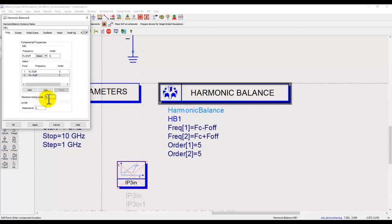So here for my analysis, I have set the maximum mixing order which I want to see in my results to 7, although I could have gone till 10. But for any practical purpose, there's no fun in going for more than seventh order products, to be very frank, because these products themselves are far from our carrier frequencies or the main tones, and anything beyond that can be easily filtered out, and they are pretty small in power anyways.